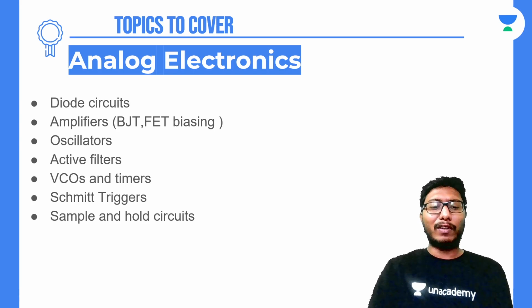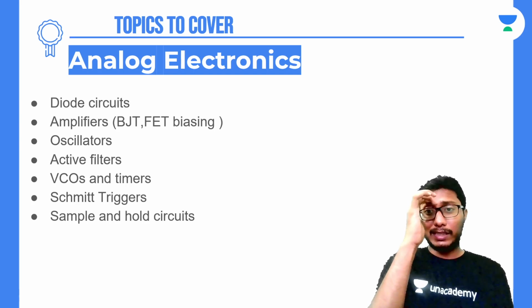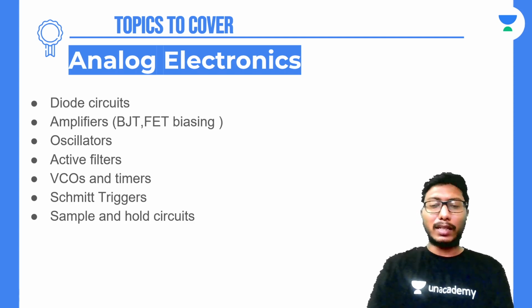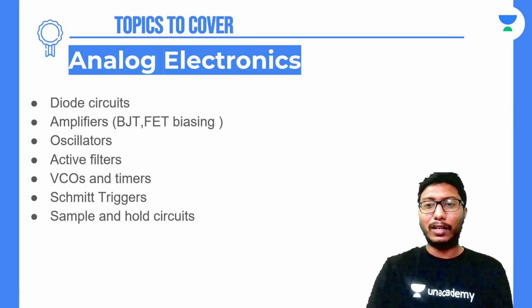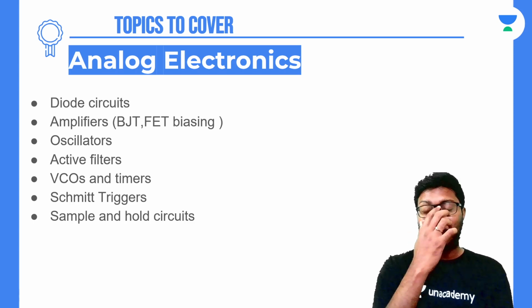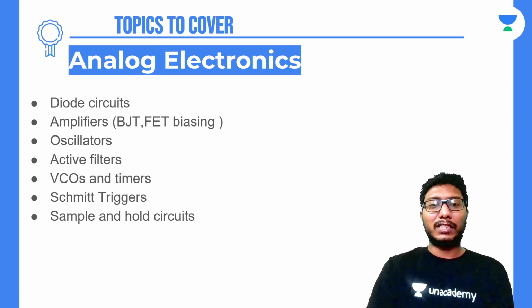And another type of amplifier you have is the anti-log amplifier. Till now we have seen that the diode is connected in the feedback. Now you can see that the diode is connected in the non-feedback path, that is, at the input terminal there will be a diode in addition to whatever voltage source you have. So this is another type of problem. And the other one is the precision diode. This is again important because it is used as a half-wave rectifier. You should know how to solve this, how to analyze these circuits, because these are again important for the GATE examination.